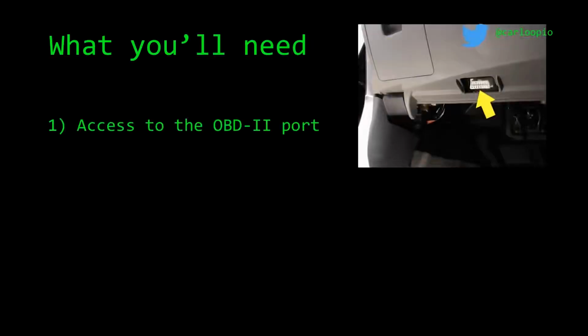So in order to get started in car hacking, the easiest way is to have access to the DLC. It's the data link connector, but more colloquially known as the OBD2 port. The OBD2 port is called that because of a regulation from the California Air Resources Board to have a standard way to read diagnostic fault codes that would affect the environment. So any fuel related, and then it became the standard for reading fault codes in an engine.